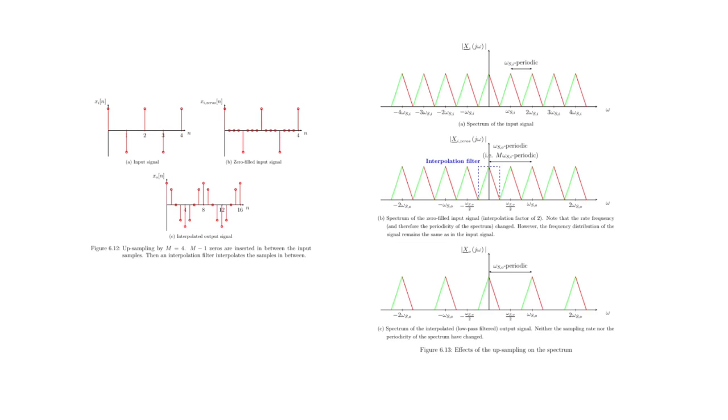But this signal is not the output of our upsampler. What follows, and it must follow in each case, you cannot omit it, is the low-pass filter. And the low-pass filter then reconstructs our signal. So therefore the following filter is also called interpolation filter.